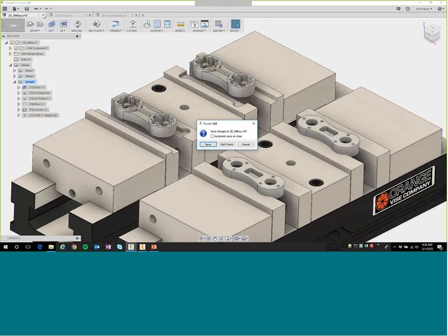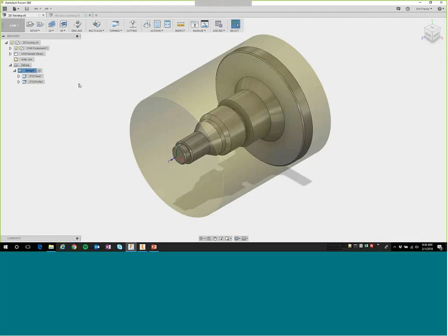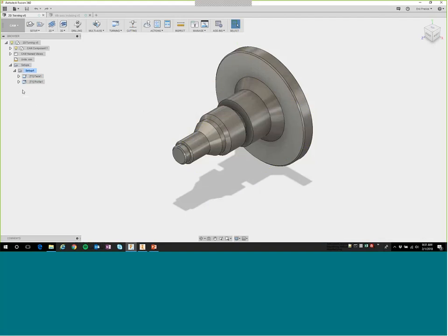Let's go ahead and jump over and take a quick look at turning. So in turning, of course, support of lathe operations or mill turn operations fall within that. We have our stock setup where we're holding the material, the stock, and a little bit of an offset. We've already got our work coordinate system set up. We've got a facing operation coming in to clean off the face. We've got a profile operation, right? Those have already been programmed in. So let's go ahead and finish this out.